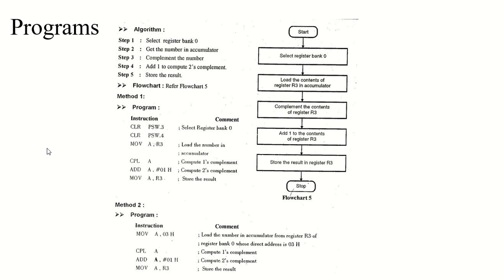See, here we have used the immediate addressing mode. We have added 1 to whatever content is present in the accumulator. And what is the content present in the accumulator? The ones complement which we have just found. So this sum will give you the twos complement. You just added one instruction and found the twos complement out of it.